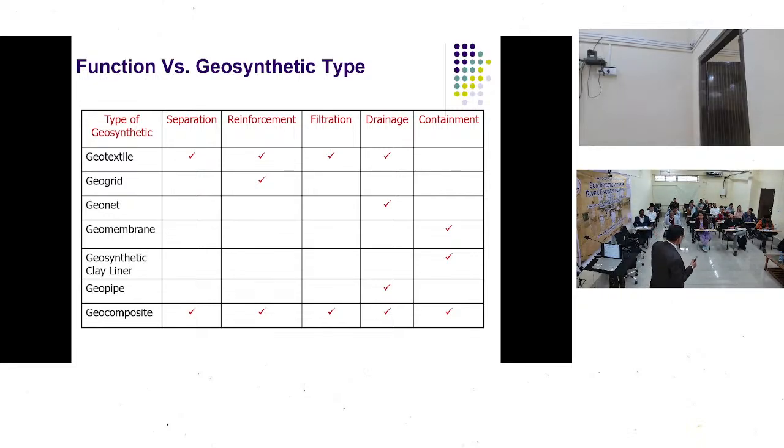Here what we are doing is having a geotextile on top and bottom, and in between some bentonite, and we form a blanket of it, and that forms the geosynthetic clay liner. So you lay the geosynthetic clay liner. As soon as you water it, the bentonite swells, and it virtually acts like a blanket. And installation is relatively easy.